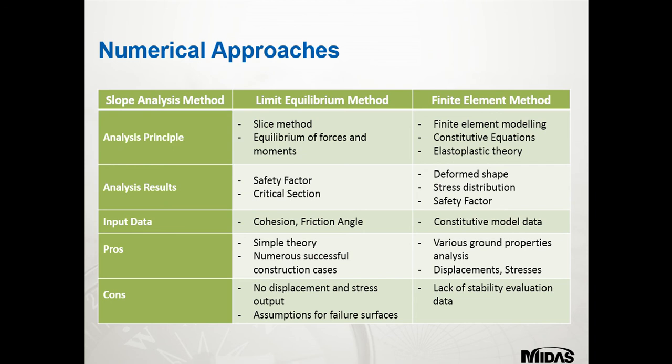For the FEM method, the input is cohesion, friction angle, elastic modulus, Poisson's ratio, dilatancy, etc. for non-linear analysis.